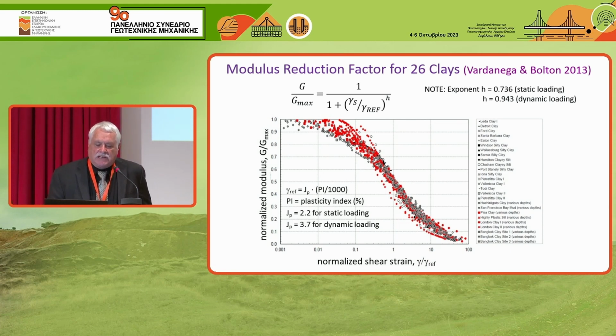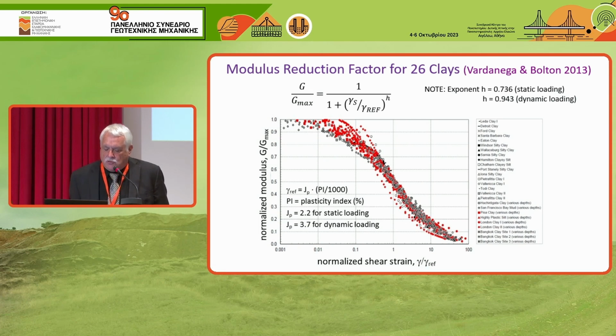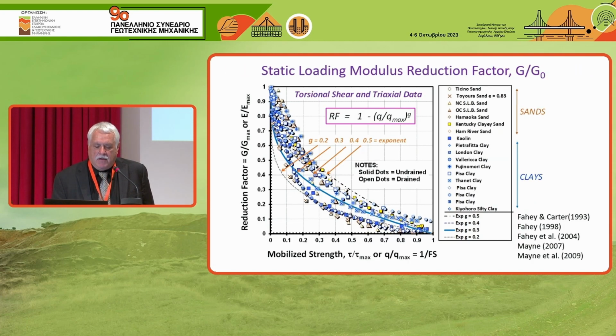And what's interesting about their method is they could take their method and apply it to static loading. You see the exponent h up there on the left upper curve, as well as this factor j p, which is shown inside the curve. So they have a method that applies to both monotonic, static loading, and dynamic loading. We do a lot of work with monotonic loading because we want to apply this to statically loaded foundations, shallow foundations, and deep foundations.